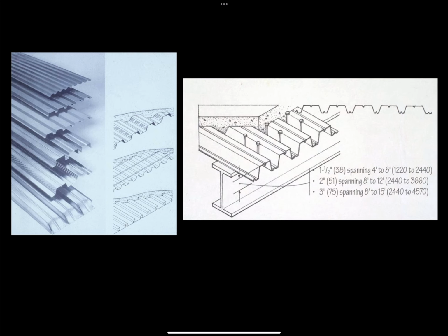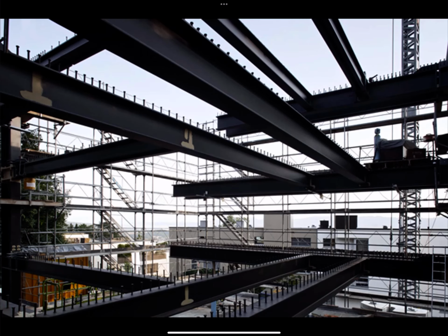This formwork then is not stripped away when the concrete cures. It remains in place, that's why we call it permanent formwork. So here you can see a steel frame being erected, and you can see that the shear studs have been welded onto the steel beams in the workshop before they come to site, and those are going to project through the corrugated steel deck and bond with the concrete. And that will make then all of the floors rigid horizontal diaphragms to help brace the building.